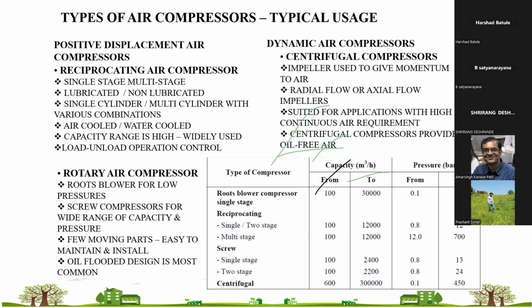Nowadays multiple terms are coined across variable drive, like VFD is there, VSD is there. So multiple terms are coined across drives. Even for the screw chillers, they are having magnetic bearings for sustainability and power savings. Maglev chillers, or magnetic chillers, are used for lower specific energy consumption. So the entire variable drive would be the same, but the application of the variable drive will be different.